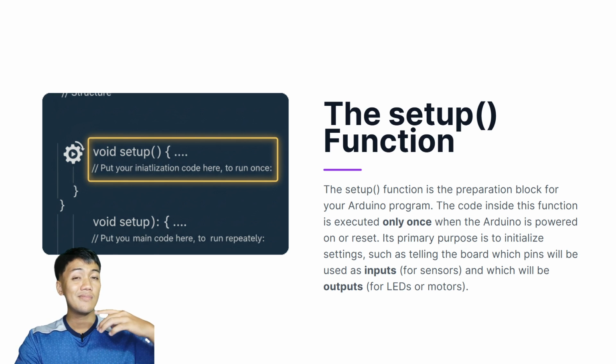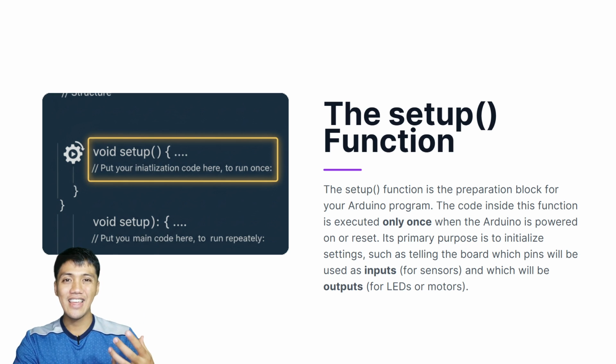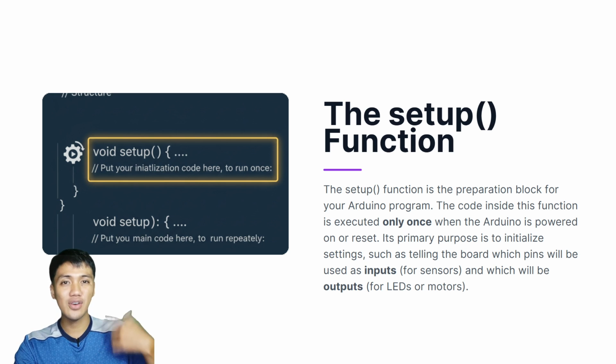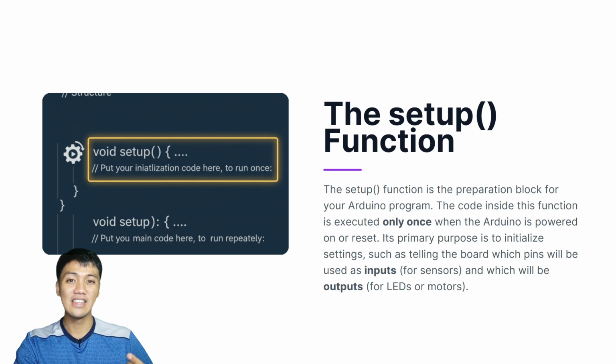Because you have to check in so that you can respond, our board, our Arduino device, can respond. It should be checking constantly, again and again, checking for physical phenomena, checking for the inputs, processing that information, processing new information again and again, and then responding to the new information again and again. So the input, process, output is repeatedly done in your loop function.